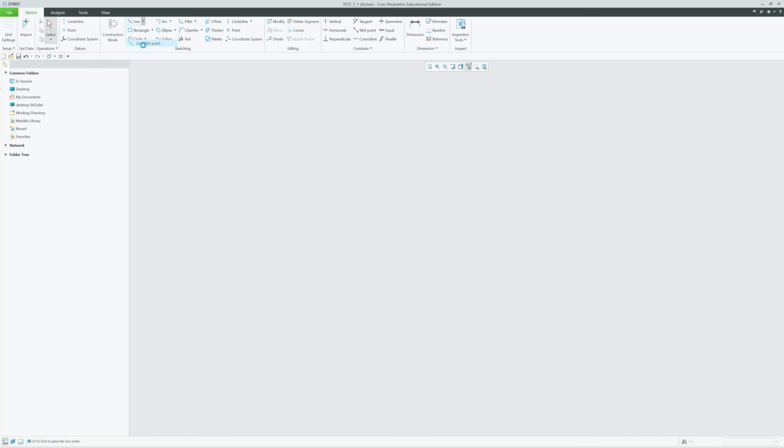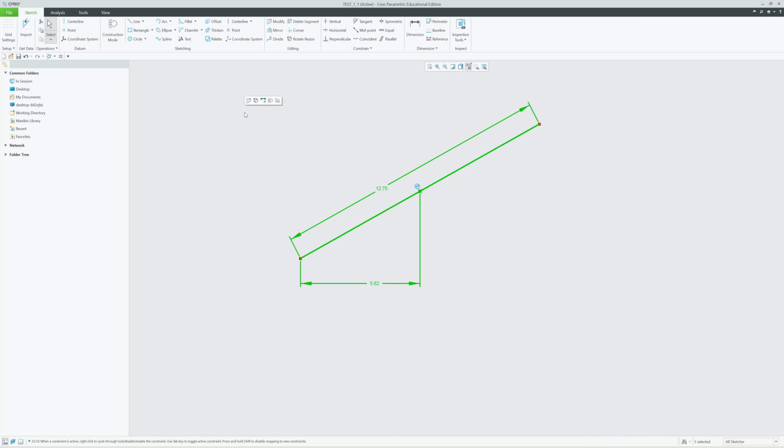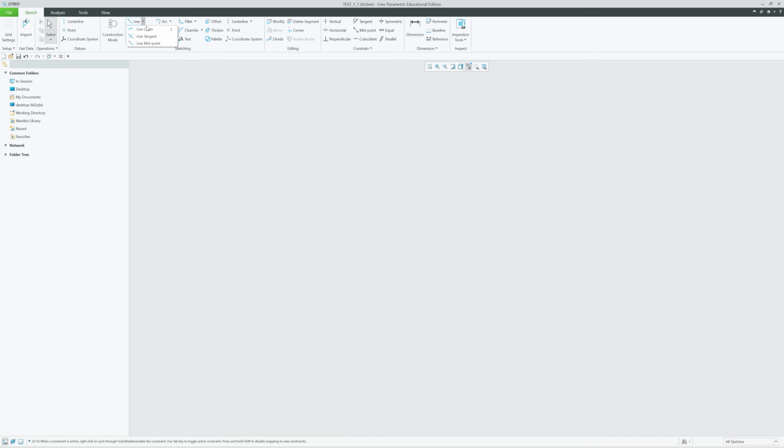And the third one is the midline. Midline is a simple one. In the first one, chain line, we used to click on 2 points. Right now we don't need that. You just click on the first point, and from there your line starts like this, whichever direction you want, and the dimensions. So that is from the center point. Hope I have explained everything on the line command. We only have 3 lines, and I have explained all 3. So let's move on to the next one.